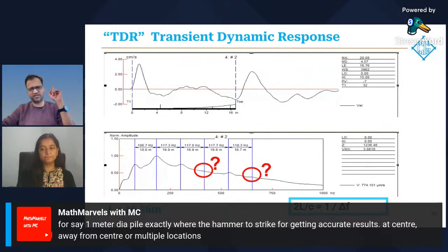Every pile, if tested properly, no matter where you fix the accelerometer or the hammer, will have its own unique signature. So no matter when or how many times you test the pile or at what location, the shape of your PIT data must be consistent. But if you're testing the same pile using different equipment or at a different time or location, and you get inconsistent results, something is wrong.